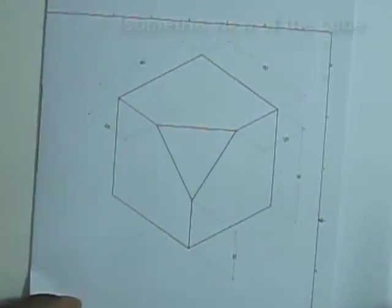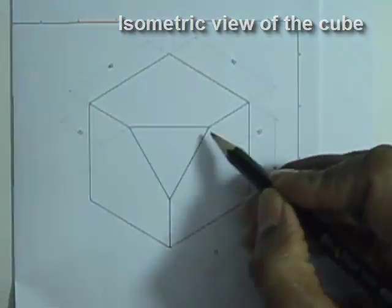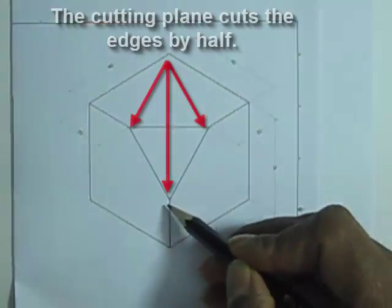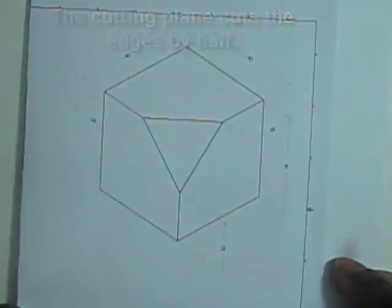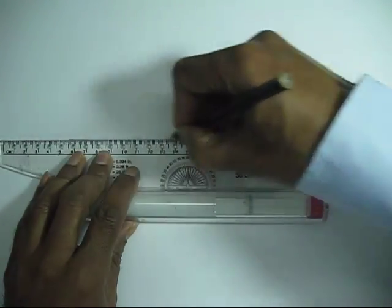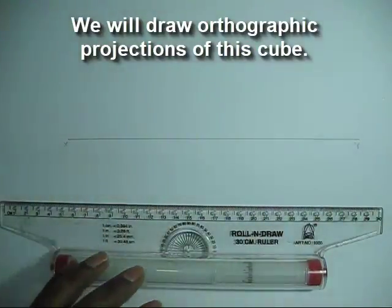This is the isometric view of the cube after cutting. The cube edges are still 40 mm, and the cut plane cuts the edges midway, that is at 20 mm. Now we will draw the orthographic projections of this cube which has been cut obliquely by a plane.